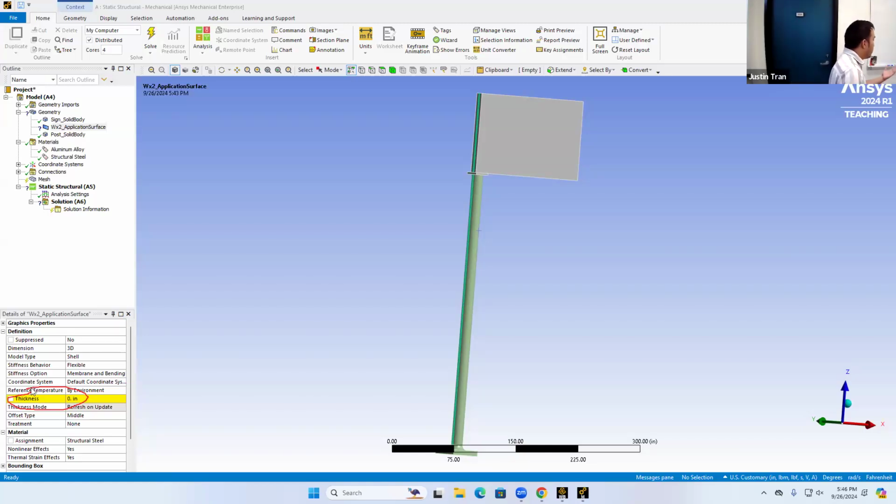And it's highlighted in yellow. That thickness is basically going to define how thick that strip actually is. But because we don't want this surface to contribute to the structural strength of the material itself, we're going to assign a very thin thickness here: 1e-3 inches, so basically 1/1000th of an inch. Basically, it's just not even going to be there at all.